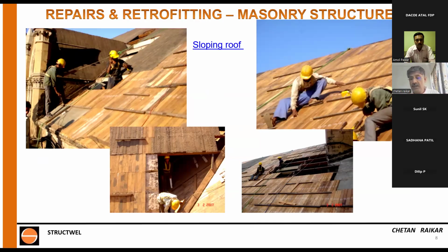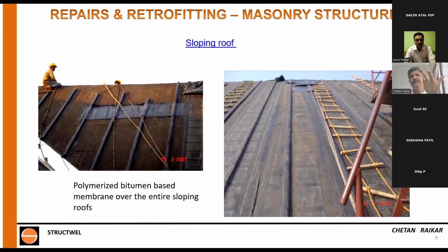So this is how the construction was prevalent earlier. We were maybe the first ones, but we provided these vertical battens, and the purlins are provided above this. So what happens is, even if a Mangalore tile cracks, the rainwater straight from the top goes out of the system.